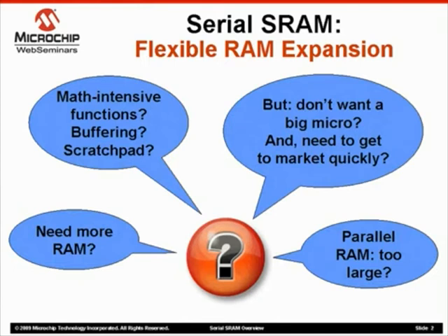Is that acceptable? Another solution would be to add additional parallel RAM, but this means a large package size as well as requiring more microcontroller IOs and additional PCB routing. Serial SRAM products can solve these issues. The rest of this web seminar will build on these ideas. Now let's look at our agenda.